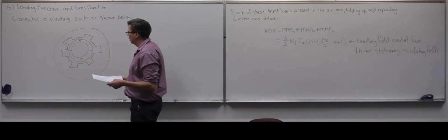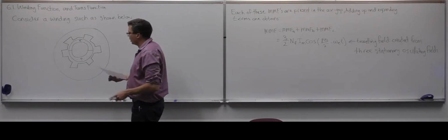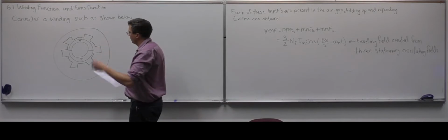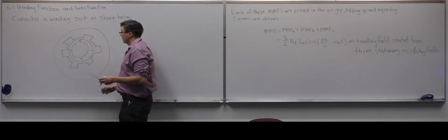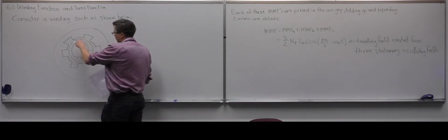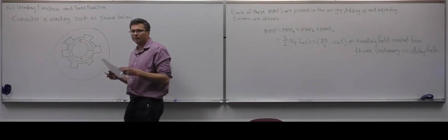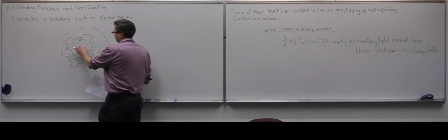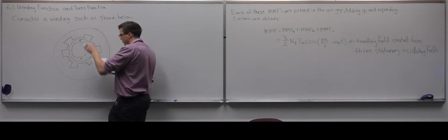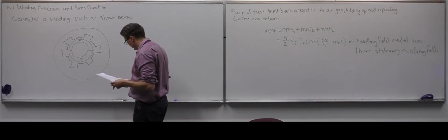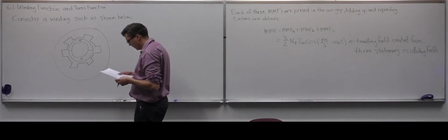But you can assume that there would be some material there, otherwise the winding distribution would not be correct because it would go into a lot of air. So there has to be something in here, but just for simplicity, for the later discussion, I won't put the rotor in there. But just keep in mind that the analysis has to have really a rotor in there, otherwise it would not give the right results.